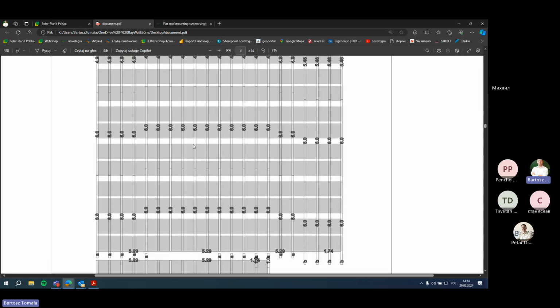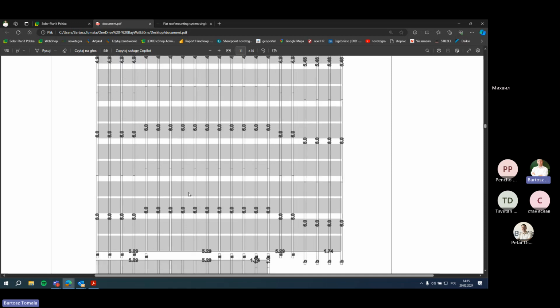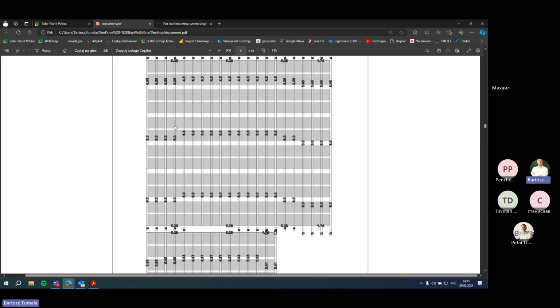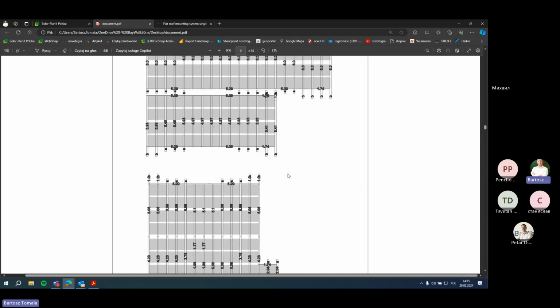It's important for the installing guys, because you will see in a moment there is the rail cutting plan. So you will see that this rail, which I cut at 4.5 meters, I have to put on these rows, not here or here or here, to make it faster and easier for the installers. They have the plan, like in IKEA furniture, let's say.